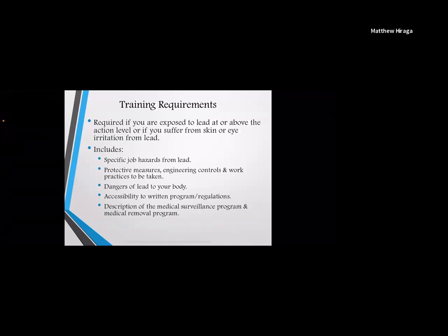Now, keep in mind that the permissible exposure limit is put into place assuming you're not wearing any personal protective equipment. So there is no respiratory protection, but you can still breathe this for 8 hours a day. When you have things like a respirator on, or you're using an SCBA or a PAPR, whatever it may be, then it's going to affect what that number actually represents. But you still should know what everything means.